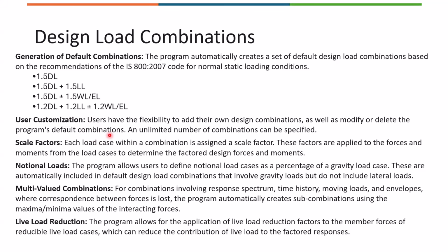It can also handle notional loads, and multi-valued combinations such as response spectrum analysis. The program creates sub-combinations using the maximum and minimum values of the interacting forces. That is, 8 sub-combinations will be generated for each combination used in the design. And then it also handles the live load reduction. For this example, we will not use these.